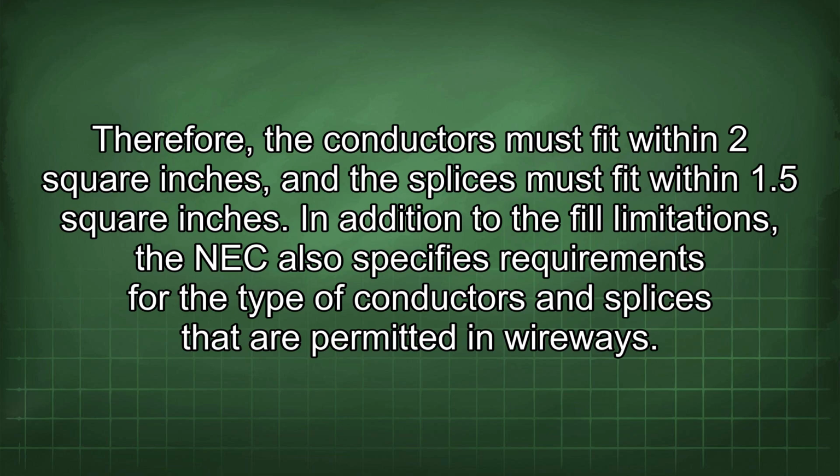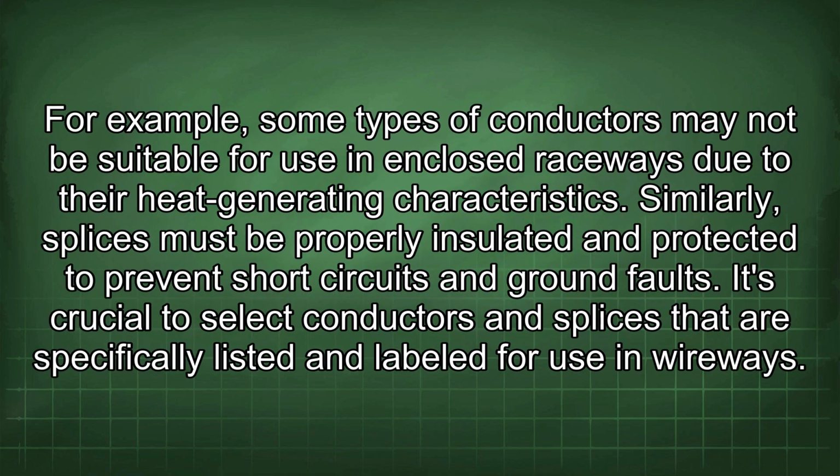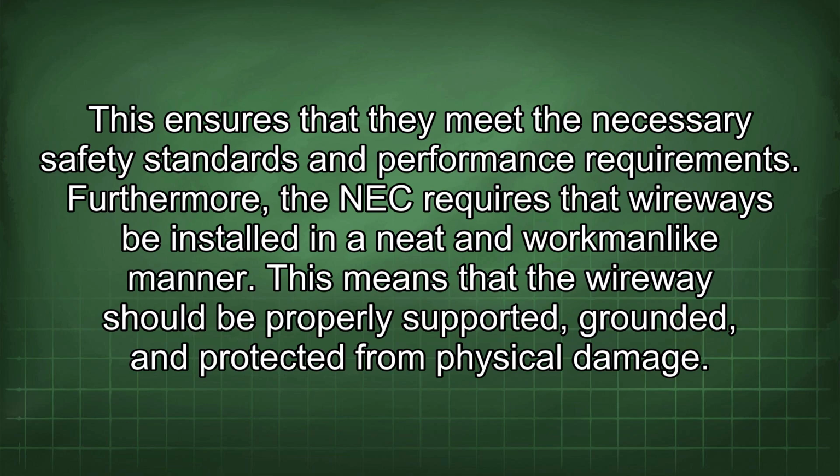In addition to the fill limitations, the NEC also specifies requirements for the type of conductors and splices that are permitted in wireways. For example, some types of conductors may not be suitable for use in enclosed raceways due to their heat-generating characteristics. Similarly, splices must be properly insulated and protected to prevent short circuits and ground faults. It's crucial to select conductors and splices that are specifically listed and labeled for use in wireways. This ensures that they meet the necessary safety standards and performance requirements.